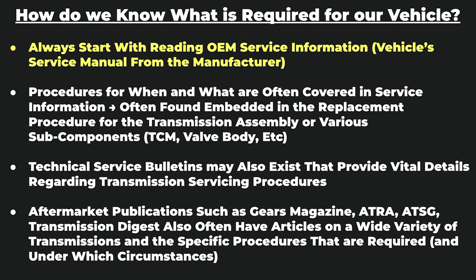So if, for instance, you have a 4L60 transmission, and you are curious about something related to relearns or resets on that transmission, you could simply search 4L60 and ATRA, A-T-R-A, on Google, and you would likely find a number of articles related to that transmission that may include things related to resets, programming, common issues, and things of that nature.